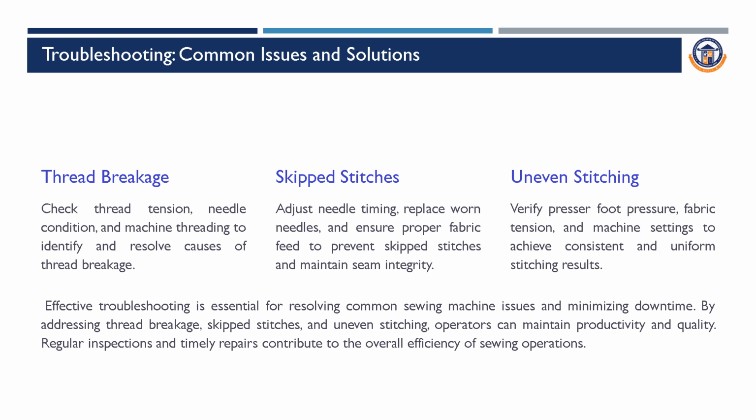Uneven stitching is another issue, which happens when the presser foot pressure changes. So verify presser foot pressure, fabric tension, and machine settings to achieve consistent and uniform stitching.